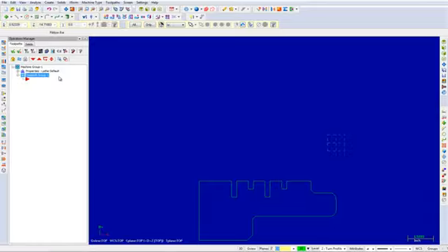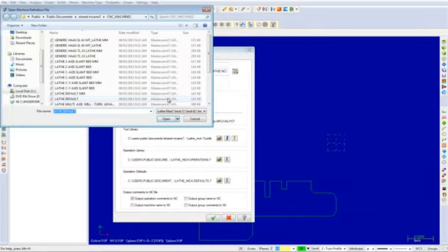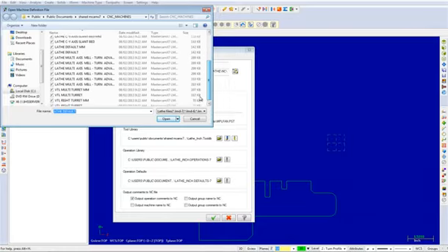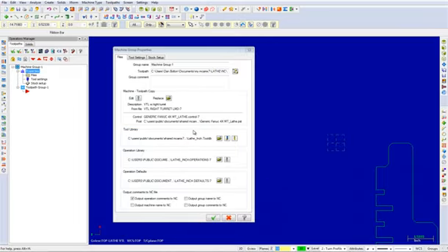Next, select the plus next to Properties and choose Files from the list. From here, pick the Replace button and select the VTL right turret definition. Once you have selected the machine, open the file. The machine should be displayed as shown. Note that the control and post file will change as well.